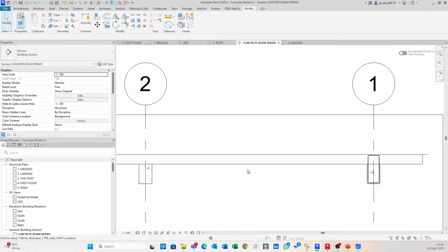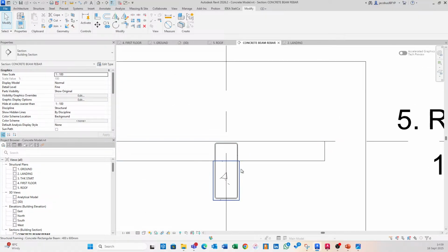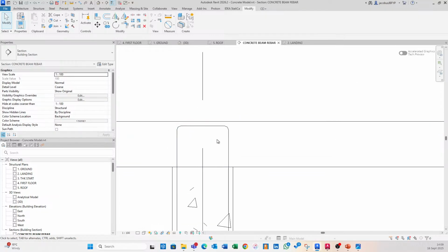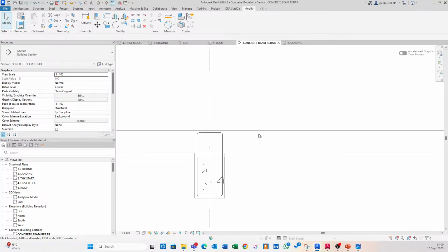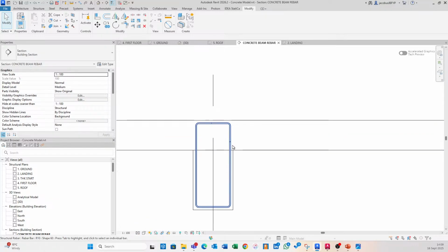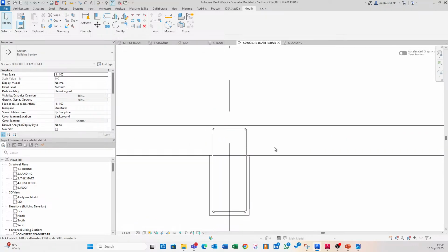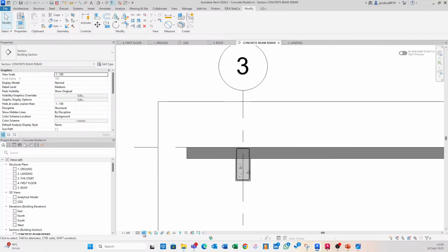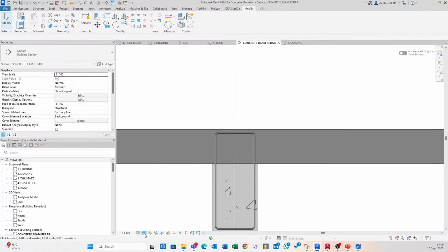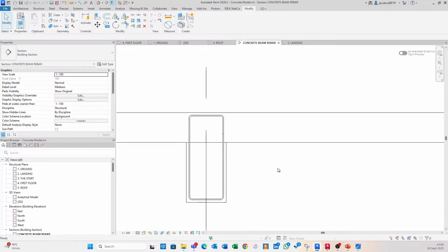I don't think we need that kind of detail when we are looking at modeling our rebar, but medium is definitely necessary because when you go to coarse, it is just a line element, which can be useful as well when it gets to detailing and those sort of things. But I think in the context of Revit, I quite enjoy using the medium level of detail. Adjusting the shading or the visual style can be useful as well, although hidden line works really, really well.